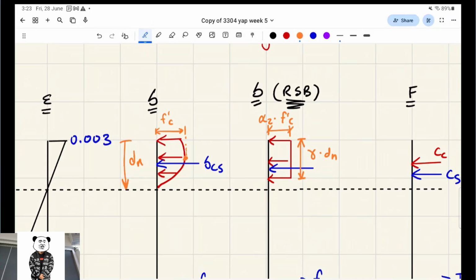In this step, we're just trying to get the position as accurate as possible, and the magnitude as accurate as possible. When we do those conservative approaches, they come in later steps. So you can't double up on how conservative you are, because it'll vastly under-exaggerate how strong the actual section is. Does anyone else have any questions so far?